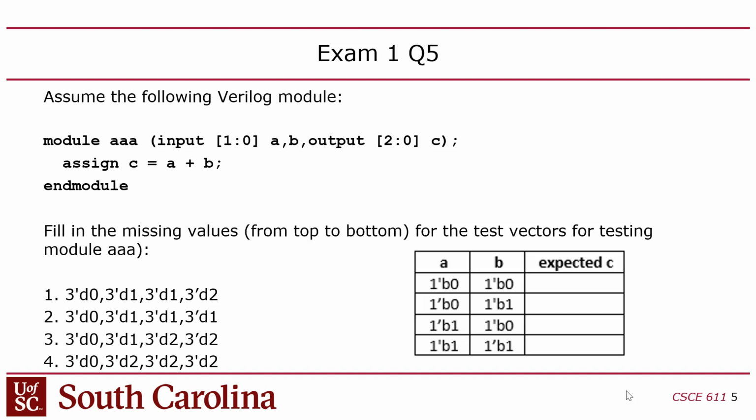So if you added 2 1s, wouldn't it just have a 0 in the highest order bit all the time automatically? Well, because the output's 3 bits and we're adding 2 1 bits, would it just not? No, it'll be okay, because if you add 2 bits, it'll use the carryout to generate a third bit. The only problem with this is the fact that A and B should be marked as having 2 bits, right?